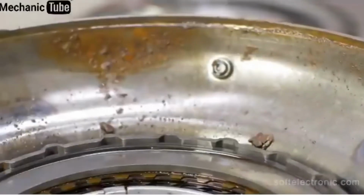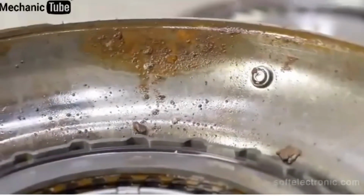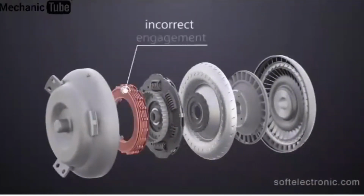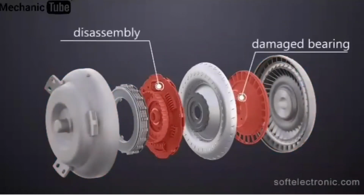In the case of metal shavings, it's necessary to thoroughly check the automatic gearbox and find out the reason for their occurrence. Causes for a problem in the torque converter may be incorrect engagement of the friction mechanisms, imbalance of the torque converter housing or some of its components, damage or disassembly of some elements during operation.